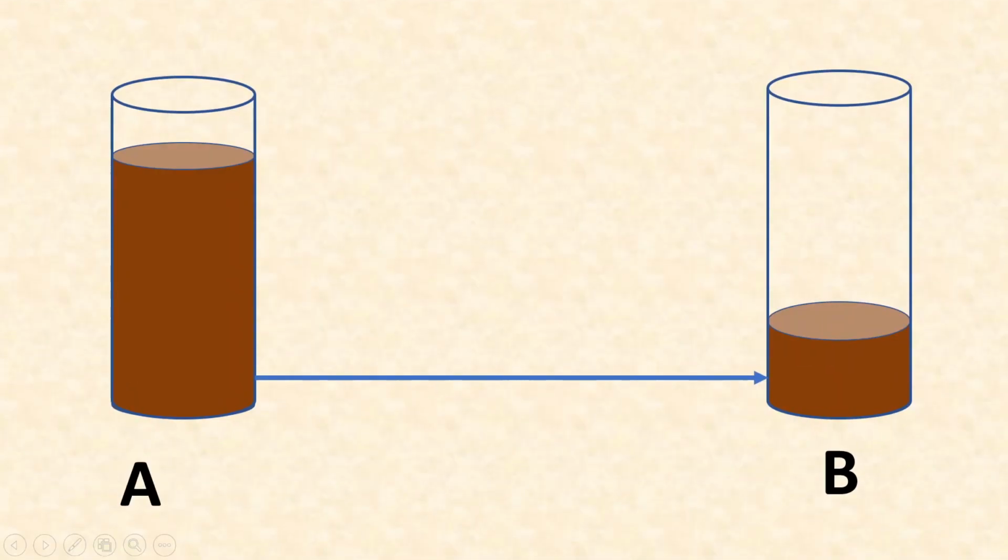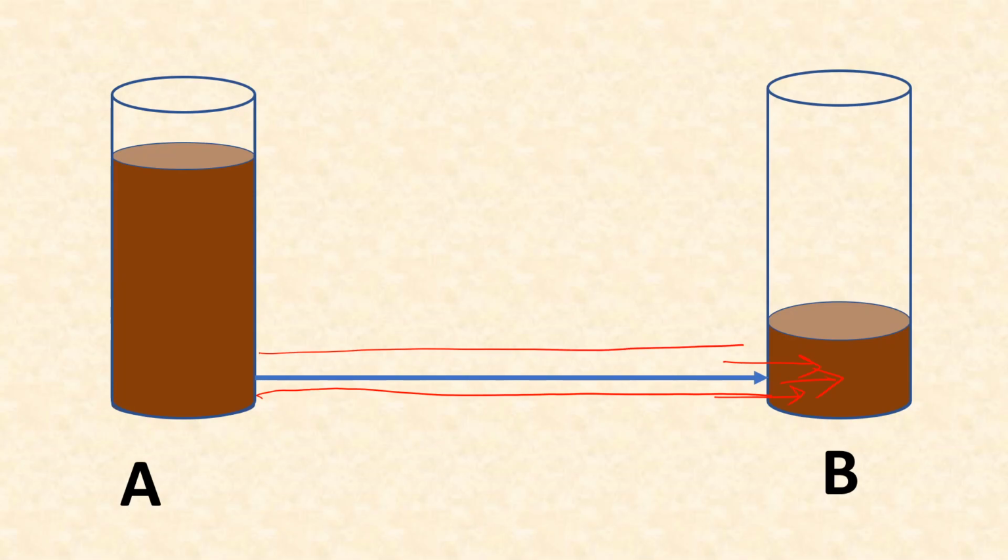Now in case of a viscous liquid, this different color is used to show that it's a different liquid having a different viscosity, let's say more viscosity. So in this case also, it will enter this tank B with a smaller velocity because a significant amount of head is already lost in travel through this pipe because of viscosity, and whatever velocity it had while entering this second tank B, that will be very easily dissipated